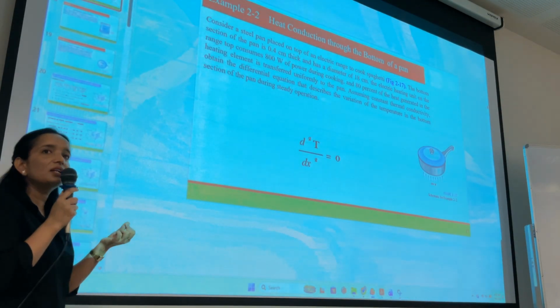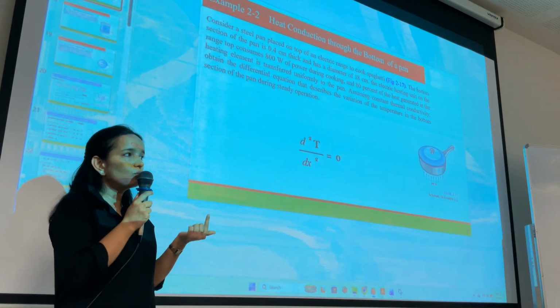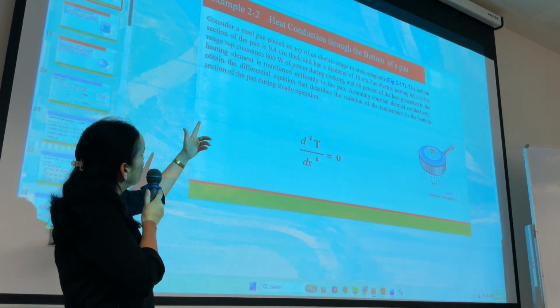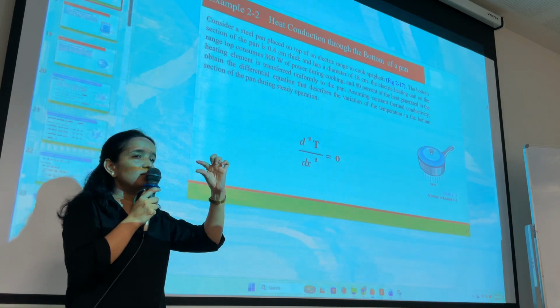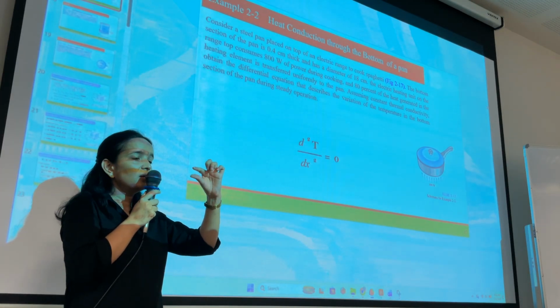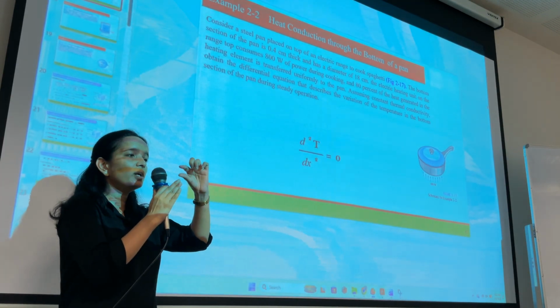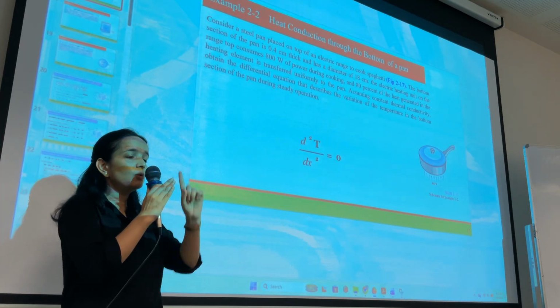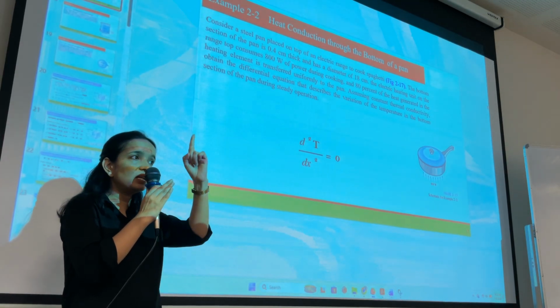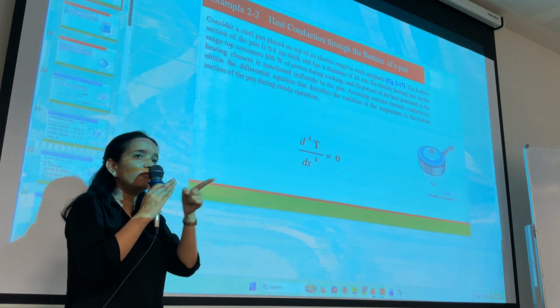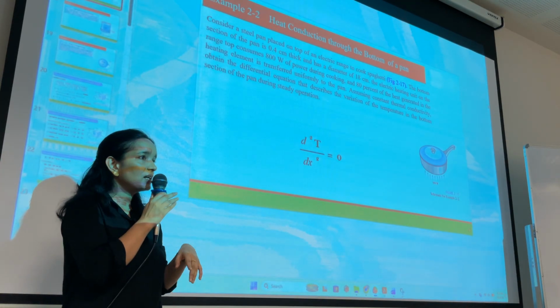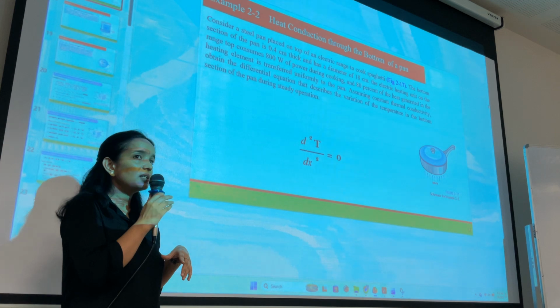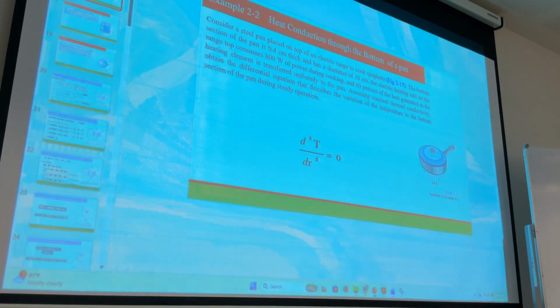The heat transfer is still happening towards the thickness. The thickness is 0.4 centimeter. This is this much thin, right? So the heat transfer from the oven to the spaghetti, which is inside the pan, will happen in this direction, in x direction, not in r, not in phi, not in theta. Understand? That's why we are using the plane wall.